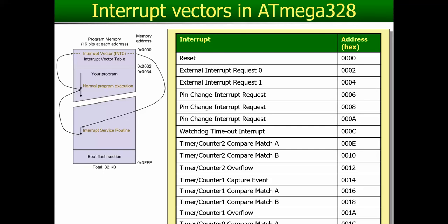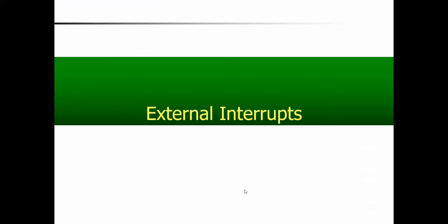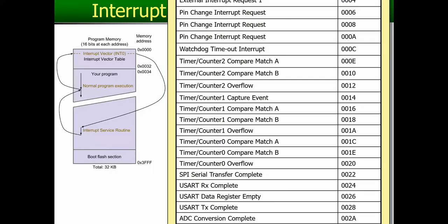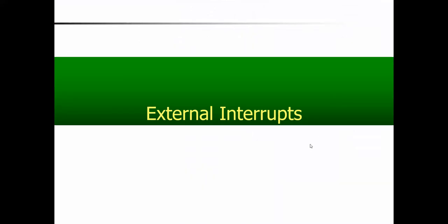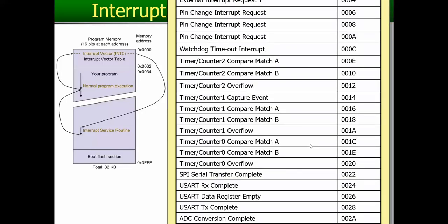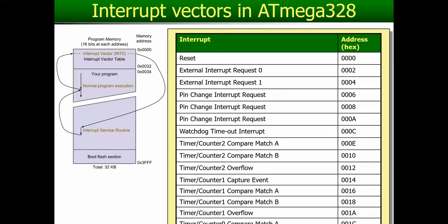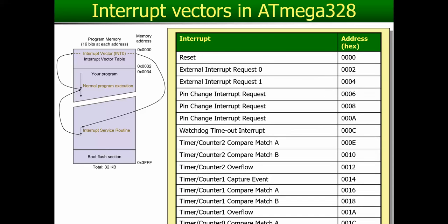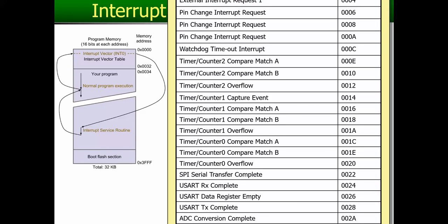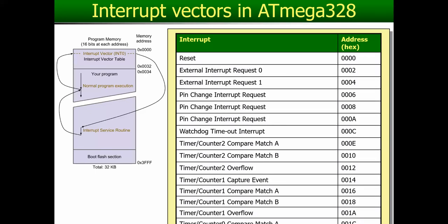Okay. In this case, it's an INT0. INT0 is the external, how to scroll this. All right, it's so hard. Yeah, INT0. Can anyone see INT0 in this? I cannot see at least. Yeah, this one is external interrupt request 0. This is your INT0.